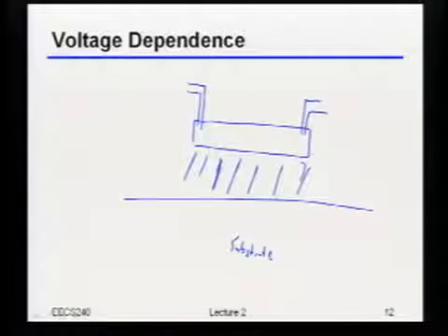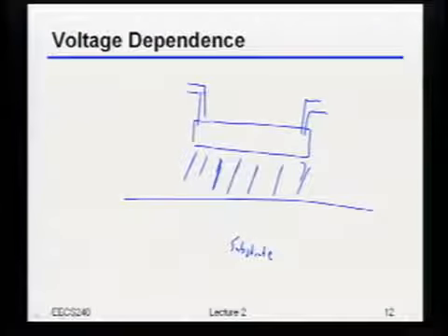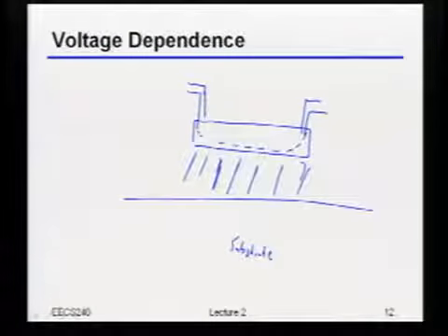Okay, so now, why is it that I claim this thing is still going to be voltage dependent? Okay, so there's a capacitance. The fact that there's a capacitance there wouldn't exactly cause voltage dependence. There's just one last thing you have to remember. Poly depletion. Polysilicon has a depletion layer, right? It's not a perfect conductor, so actually you get some depletion region sitting on that poly over there. So just like we had talked about for the diffusion resistor, same physical effect happens in the poly.